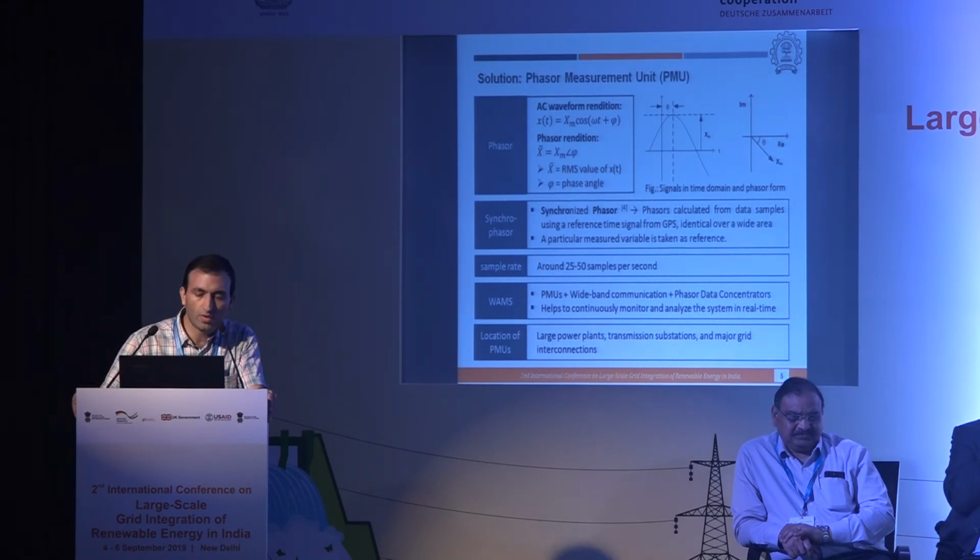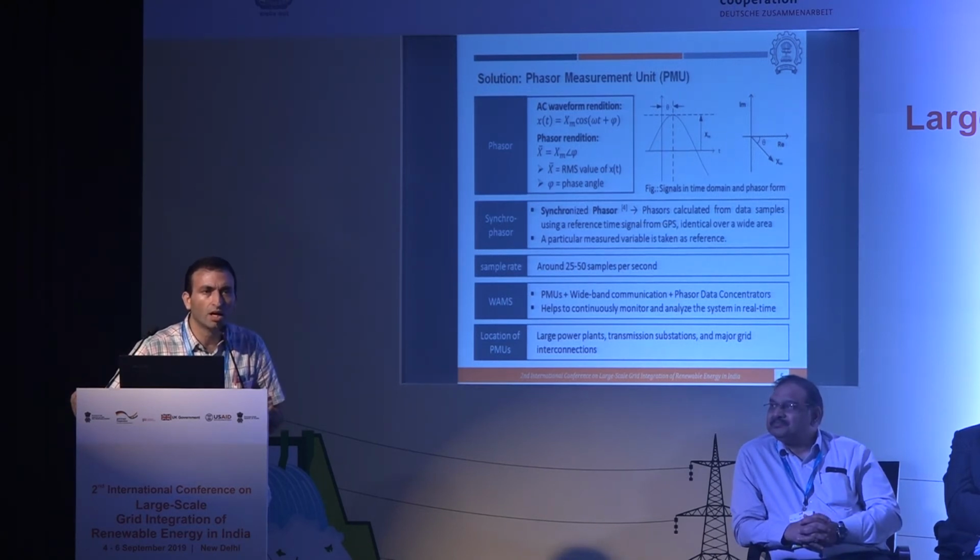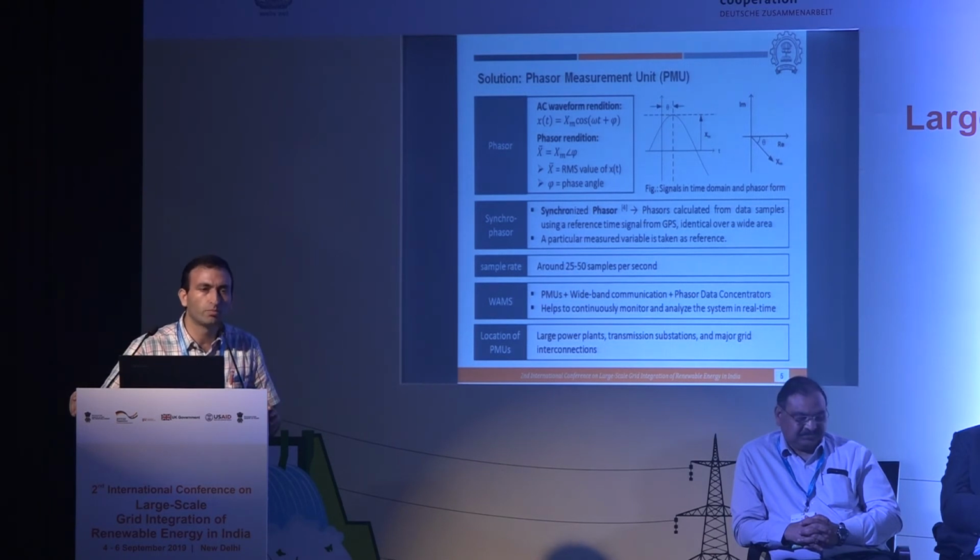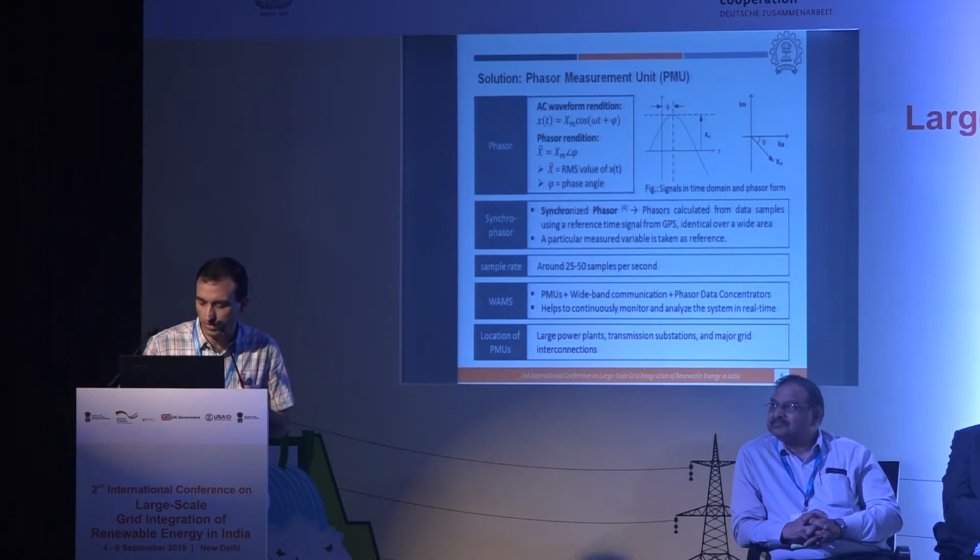What we try to do is use PMUs, phasor measurement units, which measure the phasors of voltage and currents at each substation wherever they are placed. You get fast dynamic data, with a higher sample rate compared to the conventional measurement devices we had before PMUs came up. So this PMU data, which we have available, we could potentially use as a resource for performance monitoring of these renewable energy plants.